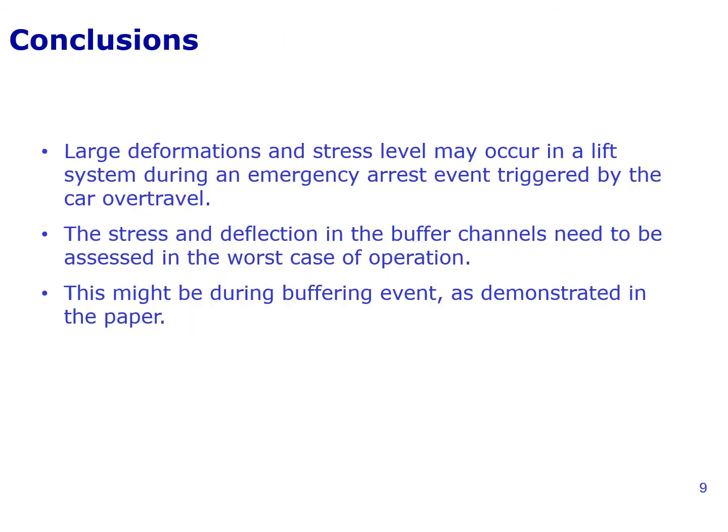Here are the conclusions. When an emergency arrest event is triggered by car overtravel, large deformations and stress levels may occur in the lift system. These stresses and deflections in the buffer channels must be assessed for the worst-case scenarios during the operation of the lift. This might occur during a buffering event, as we have demonstrated in our paper.